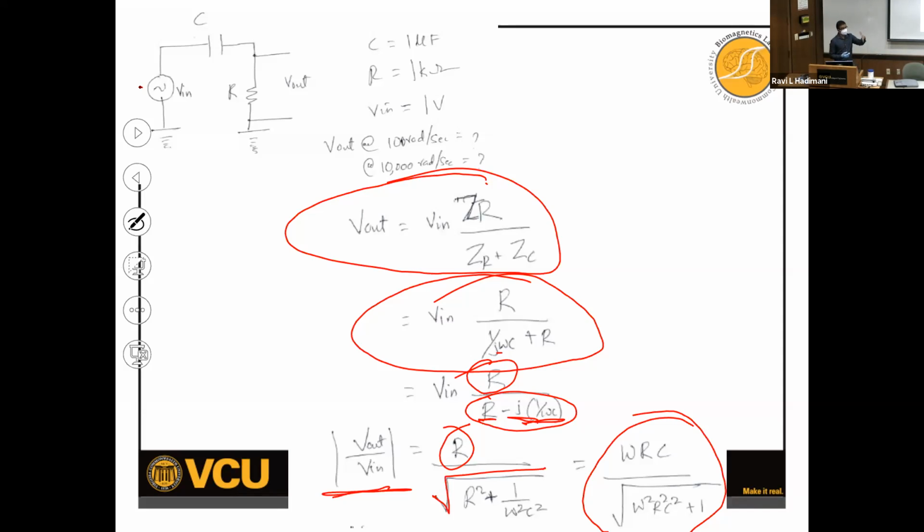Okay, that we will look at again with strain gauges in our sensors classes. There we will, but you need to remember this at that time. So we can make use of this high pass filter along with our strain gauges to only recognize high frequency oscillations. Okay, so it is a very simple circuit, right? Just a resistor and a capacitor is enabling you to filter low frequency signal.